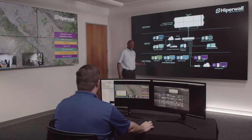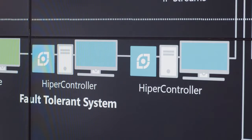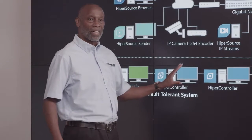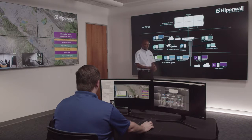Then we have Control. Control, in this case, is a fault-tolerant system. And in fault-tolerant systems, you have two controllers. So if you were to lose one controller, the other controller would still be operational. And once that controller comes back online, that content would sync and they'd have the same content on both controllers.